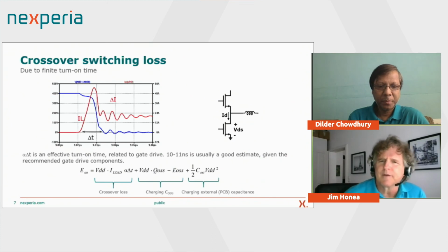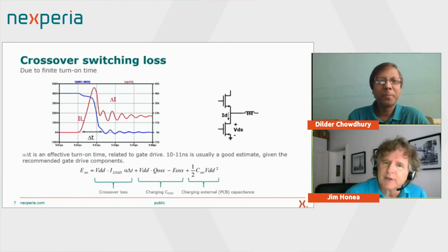One loss that you might encounter in the literature would be if that silicon MOSFET in the cascode ever goes into an avalanche clamping mode, which it is conceivable the amount of energy related to that is not alarming, but we have actually optimized the two transistors in the cascode to avoid that situation. And so we will not anticipate seeing a loss during zero voltage switching due to that factor. Mm-hmm. Right.